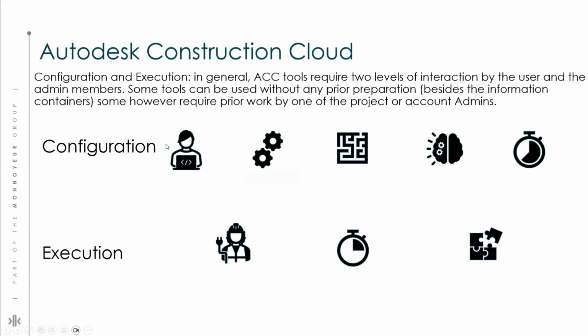Now, what happens here is we need to understand how the principles of Autodesk Construction Cloud work. There is a certain level of configuration. I actually explained this before in another webinar. What does it mean to do the configuration part? Well, it means that prior to using the tool, prior to us engaging in the tool or bringing other people to the platform, we need to work a little bit on the configuration. That means we need to set up users, we need to set up systems, we need to set up folders, we need to set up naming standards, and all that takes time.